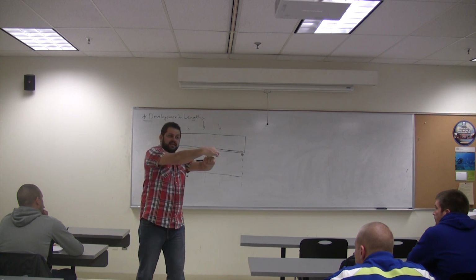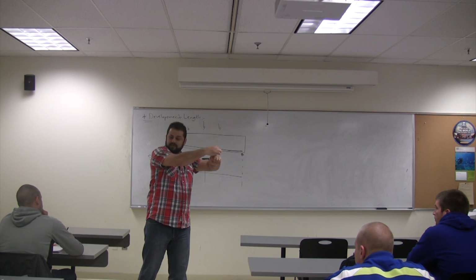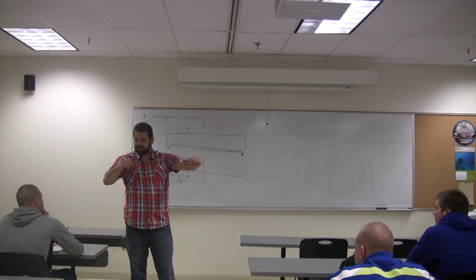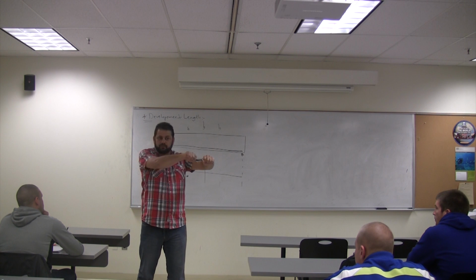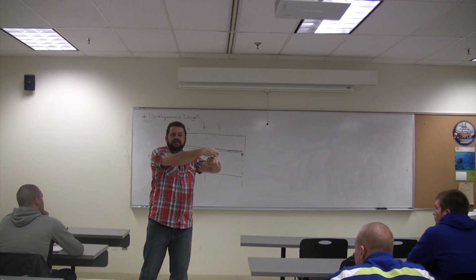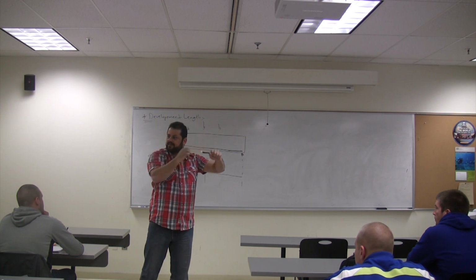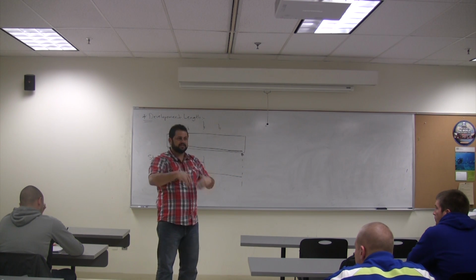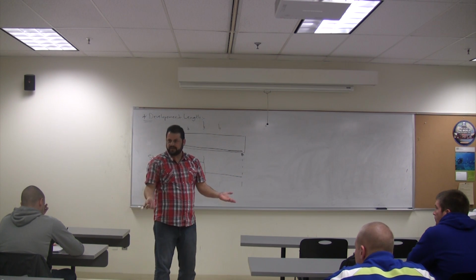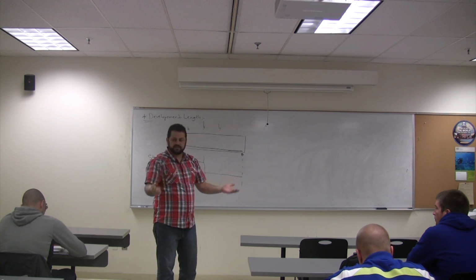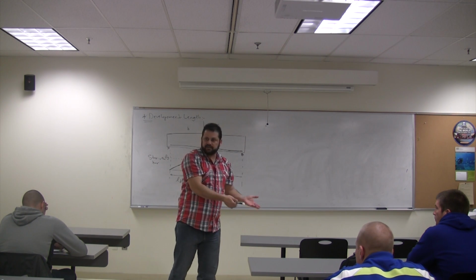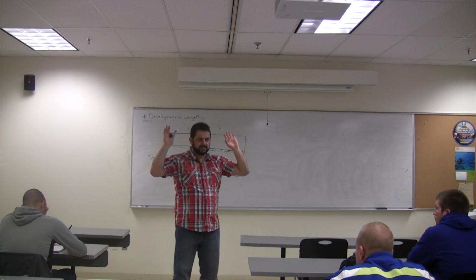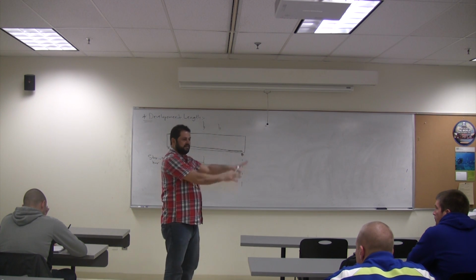And they have a strain gauge on the bar inside to measure how much the strain in the bar is. And they pull each one of them. The length at which the strain in the steel reads epsilon y, that's the development length for each series. They repeat the situation for the other bar diameters, for other epoxy coated, for lightweight concrete, for larger strength concrete. Someone did this already in the research, and that's what you have in the ACI code.